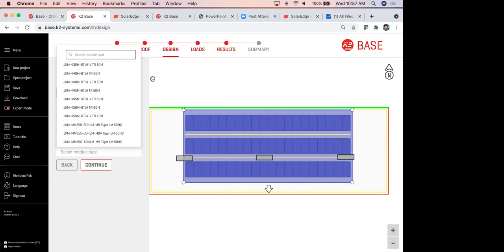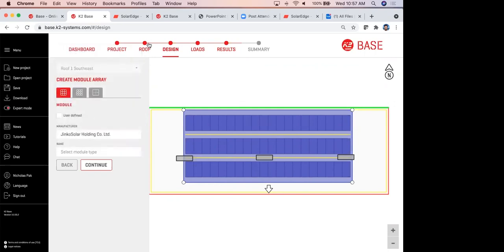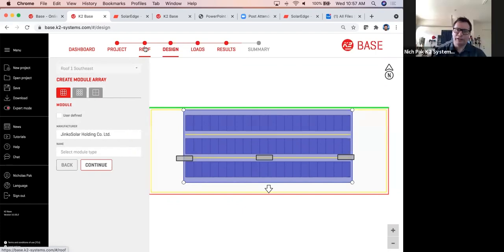Cool. And the last question that I see here is, can the tilt up solution be used on flat roofs or very low pitched metal roofs? Yes, it can actually. It comes down to what jurisdiction you're actually installing on. So we have seen tilt systems be applied to trapezoid metal roofing. We've seen tilt systems deployed to standing seam as well. It really depends on what the jurisdiction of where you're installing allows for those particular types of installs.